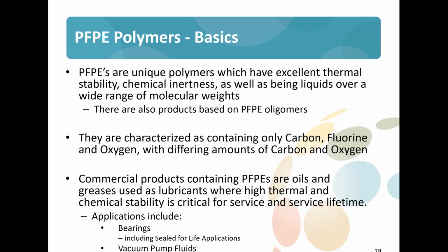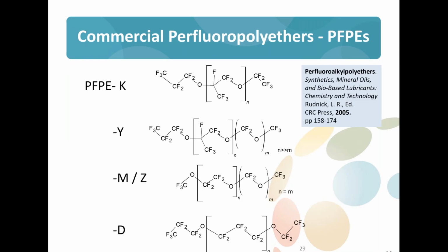And largely, these are commercial products, particularly oils and greases, used as extremely high-end lubricants where you need high thermal and chemical stability for very severe service or service lifetime, where you might put a pump or something together that's sealed for life, as an example: bearings, vacuum pump fluids, and whatever they may be. Very, very critical applications.